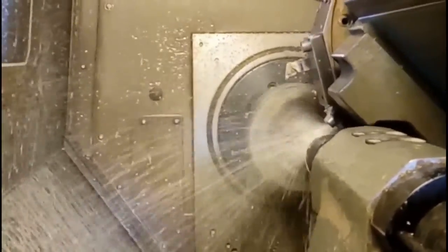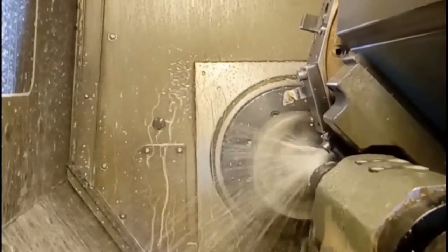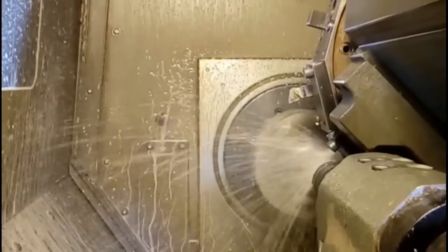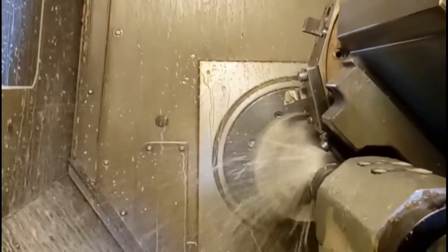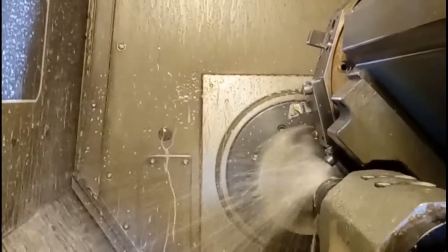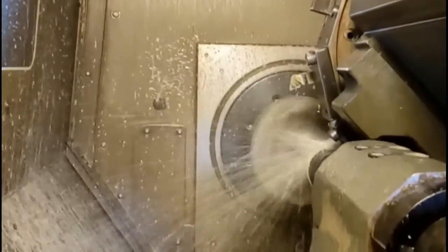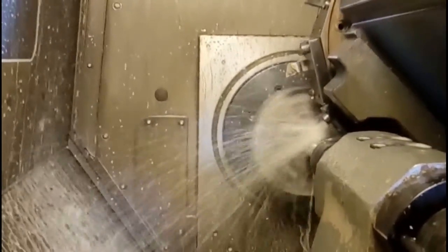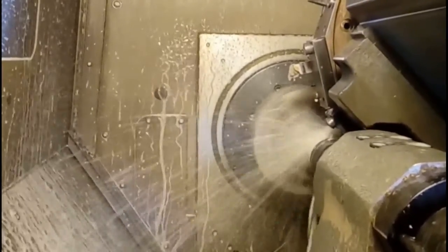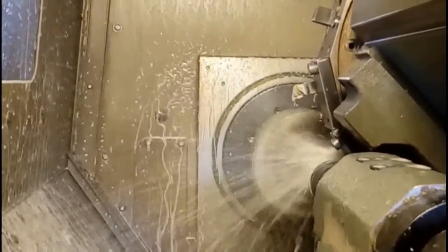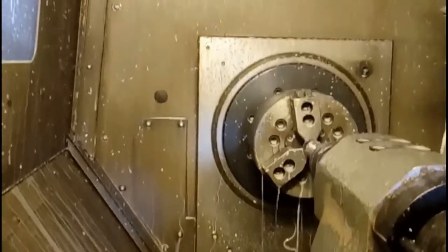The thread formation on the workpiece. From this, I can create the square threads on the workpiece material, which is a normal threading operation available with our CNC machines. So we won't go for any special program, we won't go for any special tooling for creating the square thread. Normal square thread we can make with the CNC turning center.